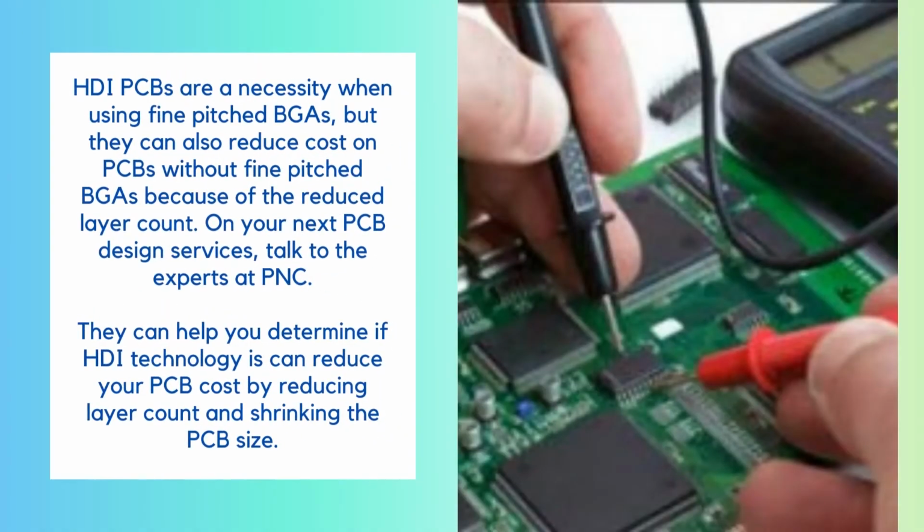HDI PCBs are a necessity when using fine-pitched BGAs, but they can also reduce cost on PCBs without fine-pitched BGAs because of the reduced layer count.